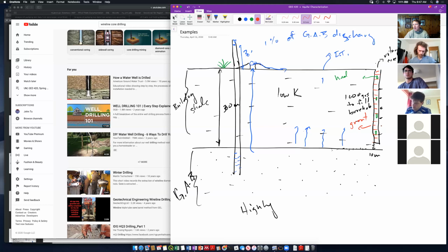The reason why we grouted this whole thing in is now, first of all, grout hydraulic conductivity is way higher than the clay. So bend your mind around that. Cement has a lot higher hydraulic conductivity than clay. All right. This was like a high K zone for us.